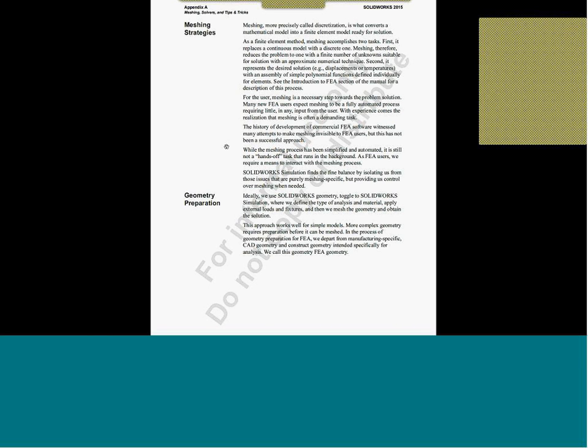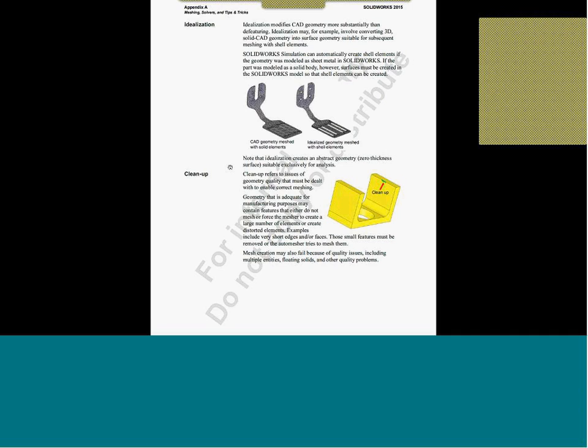Mesh strategies, geometry preparation, mesh defeaturing. This should be okay. Idealization we discussed a little bit. Cleanup, these topics are useful in terms of cleaning or idealization of the geometry. When a geometry is imported, sometimes it might have some small entities here and there, and that can create problems. So it is sensitive and useful at those locations only, but other places it's fine. Other way around, if the geometry is created in SolidWorks, typically we have a clean geometry.